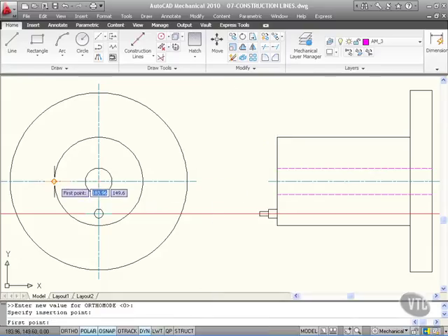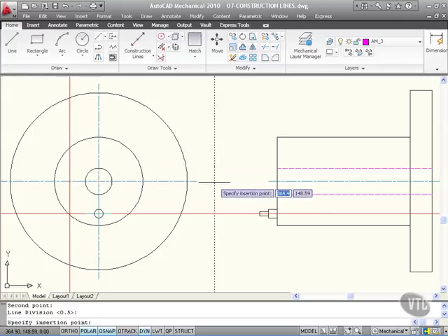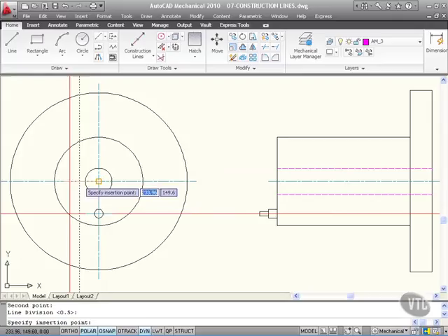So I'm going to go quadrant there, quadrant there. Then it asks line division. You don't get this in the regular AutoCAD, but basically you can specify how far you divide your mid between 2 points. I want it half and half, so I just press enter to accept the 0.5 default. As you can see, half, half.